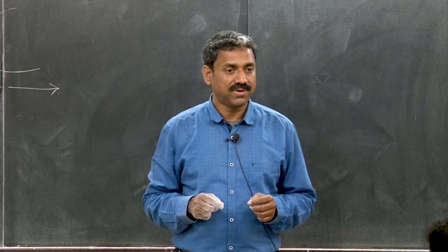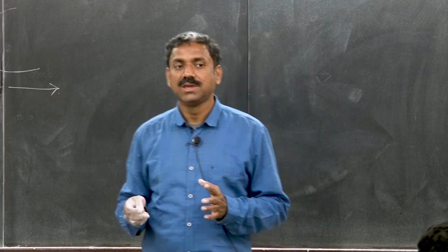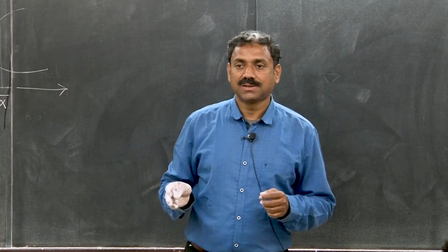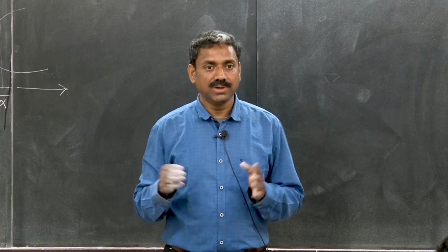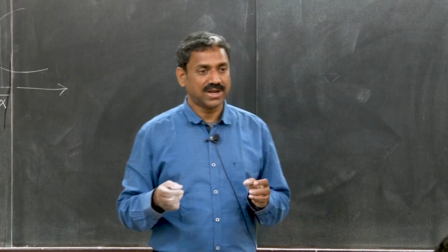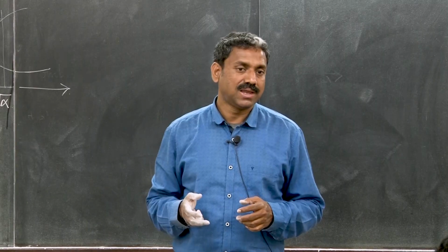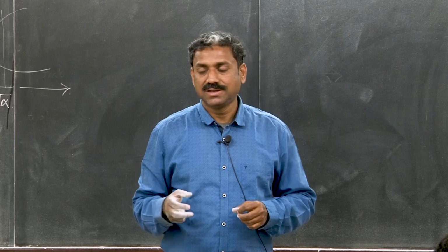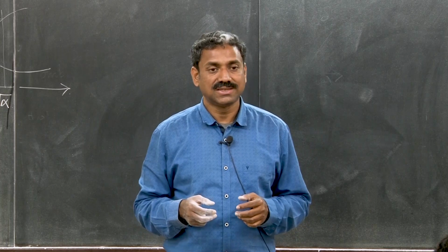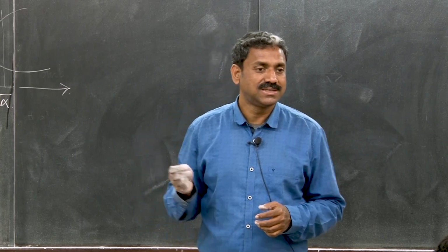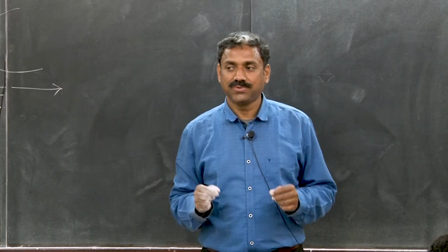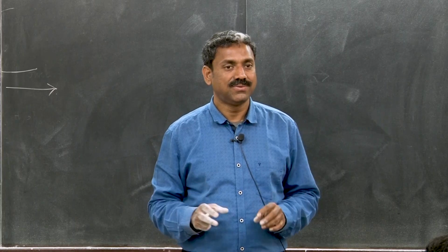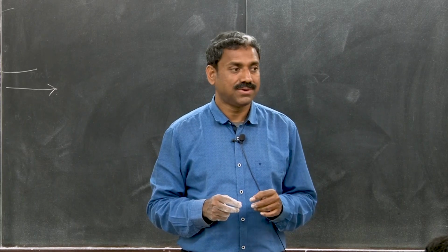Those are notoriously imperfection sensitive, and there are other systems which do not show bifurcation but show snap through. There the stable to unstable transition occurs dynamically, although we are capturing that using static analysis. It actually happens dynamically, through snap through, with release of kinetic energy dissipated as heat and things like that. We have also demonstrated a system which shows combined behavior, a snap through as well as bifurcation combined.